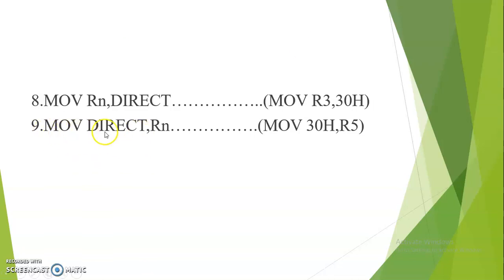Now we will see the 9th combination, which is the reverse of the 8th, which is MOV direct, Rn. Now what will this instruction do? We'll see the example of this instruction, MOV 30H, R5. This instruction will copy the contents which are there in the R5 register of the selected register bank to the location 30H.